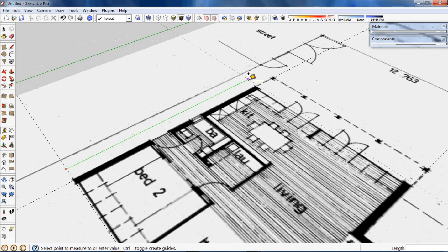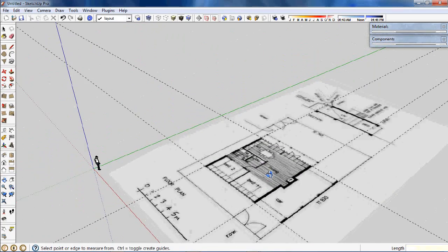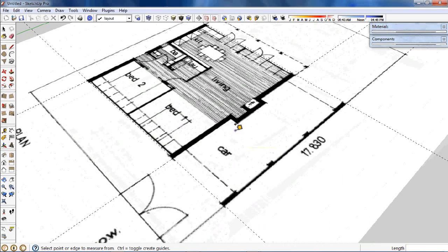The only other things that I might need as a bit of a guide for this set out here might be where this pop out in this wall goes, and once again, if we are using brick for this wall construction, we'd probably want to use something which respects brick dimensions. So I'll pull out from here, and I'm measuring something around about 3.6 metres there.